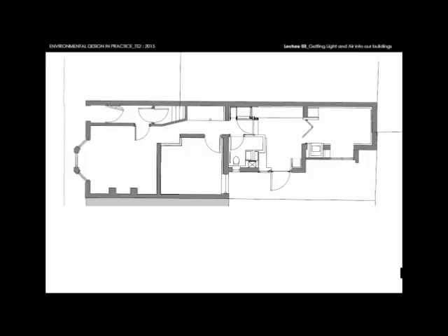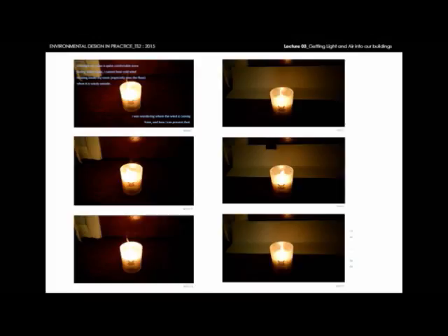Just to remind you, my home obviously is a series of rooms, but there are opportunities for cross ventilation. But most of my rooms can only be ventilated through one window. It's single-sided, that also. This less so, because I can actually open one and ventilate out to the other, and of course I can open the front door and ventilate out through there. I'd like you just to test that with something very simple as, on your diagrams, show me which ones are open, show me which ones are closed, and then see what the impact is in terms of air movement through your house. You might pick a day that's just a little bit windy, just to accentuate that.